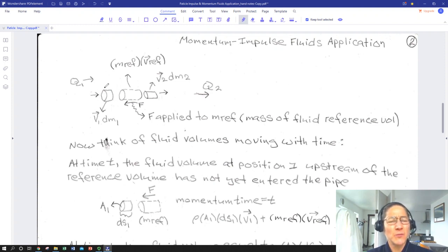We could say maybe the momentum of this body, and relate it to the momentum of this body. There's been a change. They're the same volume. They're going to have different velocities, and something in here is happening to the reference volume with a force impulse that is somehow going to change V1 relative to V2 if it's non-zero. And we're saying it's frictiony, so there's a high coefficient of friction in this pipe, so there's definitely a force impulse.